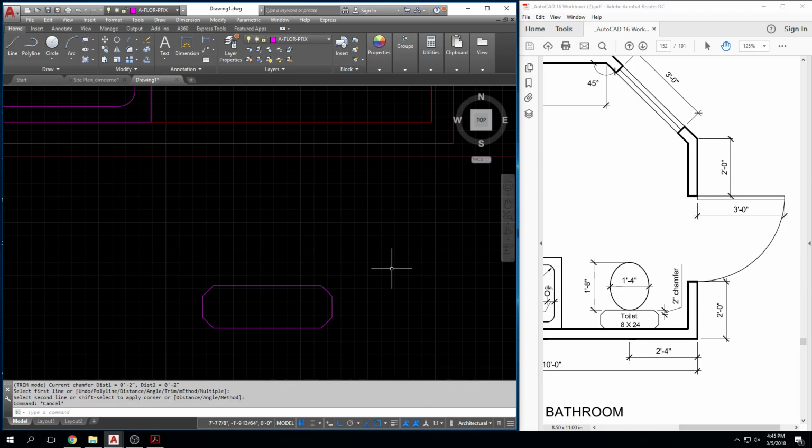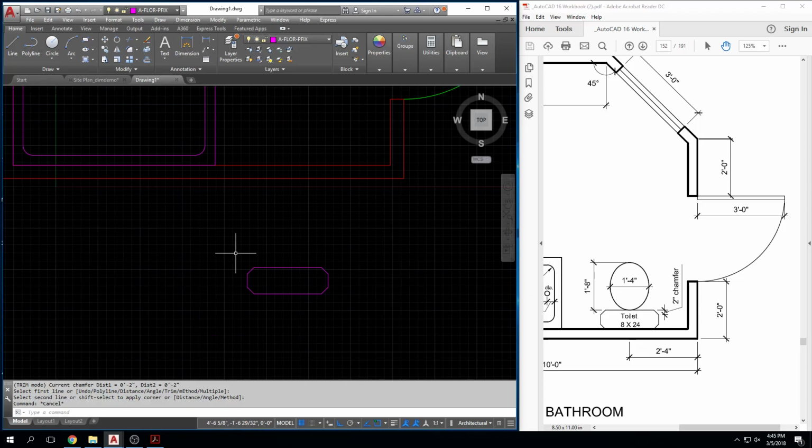We haven't done M2P for a while either. Let's do M2P. You guys are probably like, what's M2P, right? The best tool ever. I want to take this tank and I want to center it from between these 2 points. I could click on it, I could measure this and figure out the midpoint. I could draw a line across here and center it, but I could also do M2P.